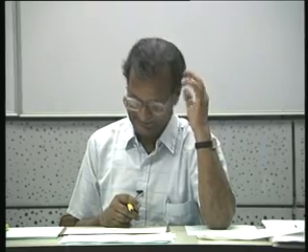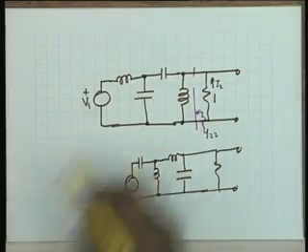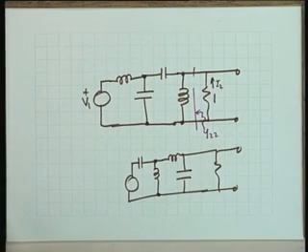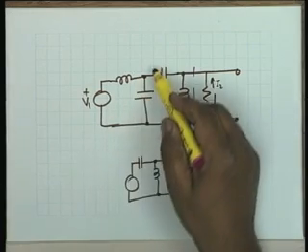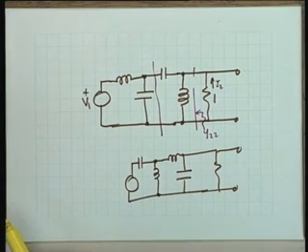If we had 3 zeros at the origin, we would have another inductor here, another inductor in shunt. Then could we have two inductors instead of an inductor and a capacitor? No, 2 inductors at the start should not be allowed because it is equivalent to 1 inductor. That you have to check.